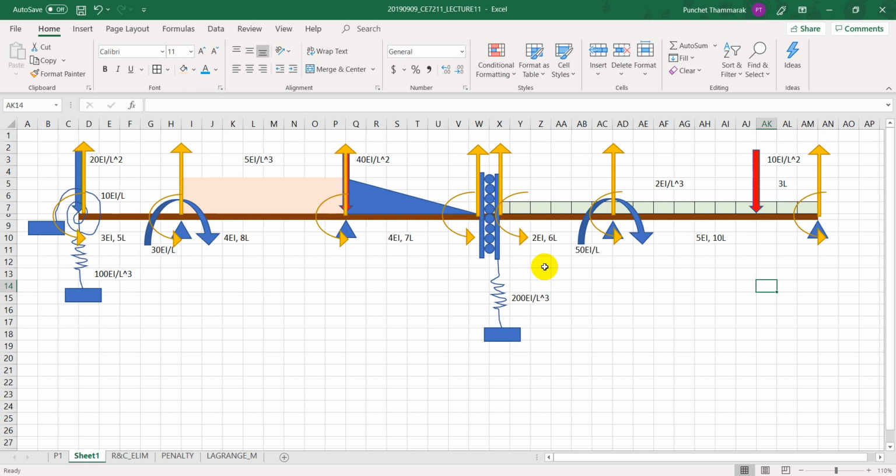Now you get displacement solutions. You obtain support reactions, all the actions on the individual member, and finish it up to the SFD, BMD. Make it a complete work.